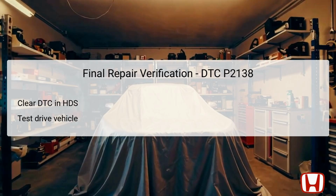After addressing the issues that led to the DTC P2138 being flagged, it is essential to perform a final repair verification. This includes using the HDS to clear any stored DTCs, including P2138, which ensures that the fault codes do not persist.